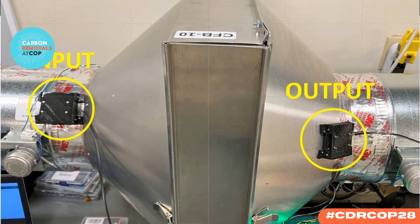Yeah, that's right. The sensors are an SCD30 made by Sensirion, and in their application recommendations, they say the sensor shouldn't be located in the direct path of the air, because that would cause an incorrect reading. So we mounted them in the boxes that Ling made on the outside of the chamber.